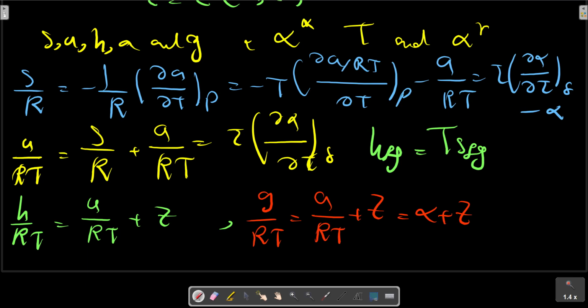The starting values for this iterative process are the pressure from an equation of the form given before, with the liquid density from given experimental data as discussed earlier in this section. This method of using an equation of state to calculate the properties of both the vapor and liquid phases has the distinct advantage in accuracy of representation that no mathematical integrations are required in the process.